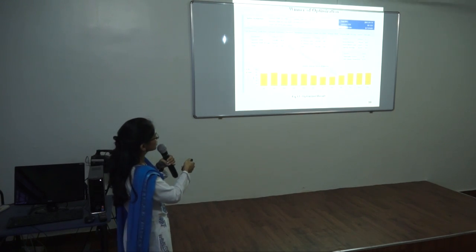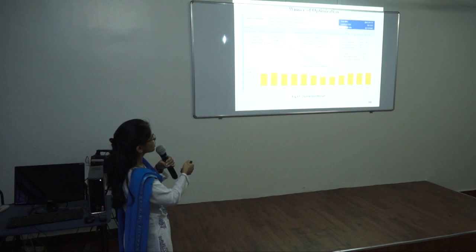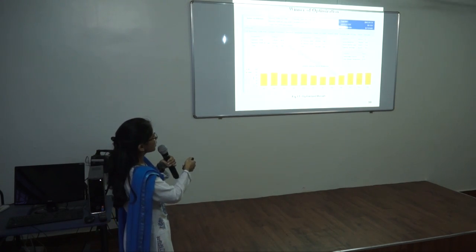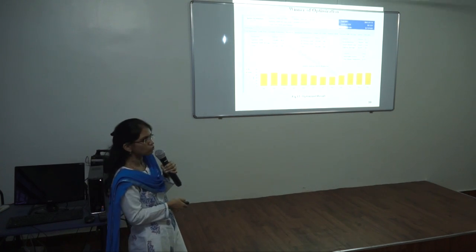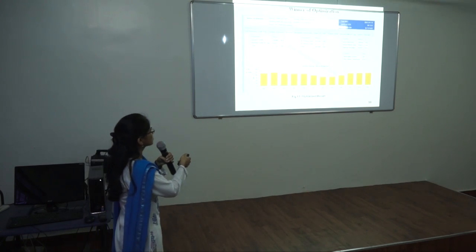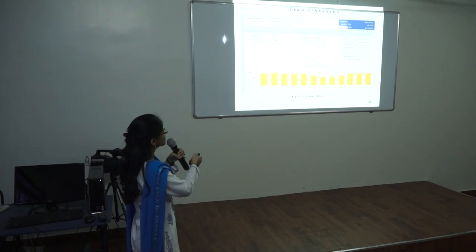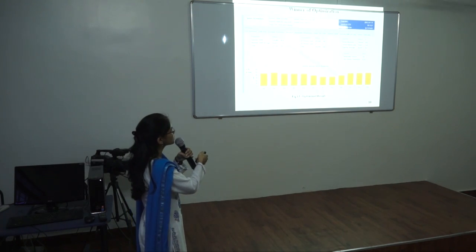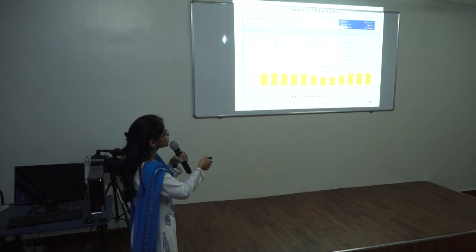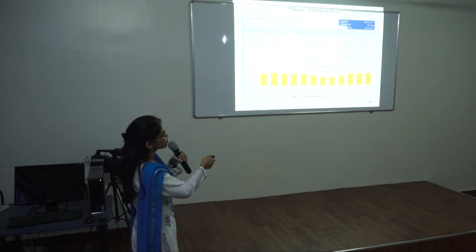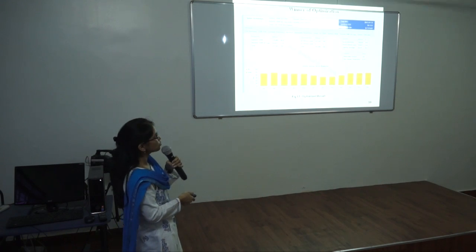Annual electricity production is 377,541 kWh per year, out of which solar contributes 333,869 kWh per year, which is nearly equal to 88.4%, while the wind system contributes less energy, about 43,672 kWh per year, which is nearly equal to 11.6%. This configuration has the lowest net present cost with a minimum cost of energy equal to $0.1323.